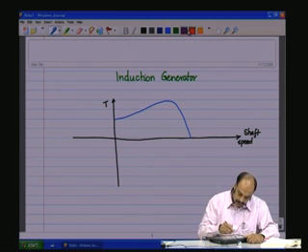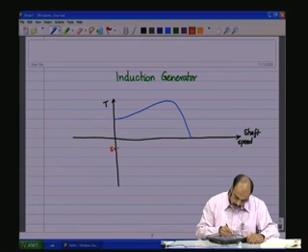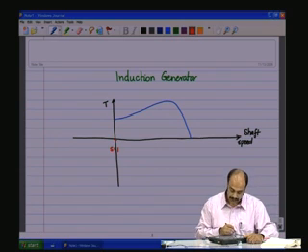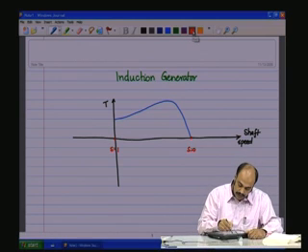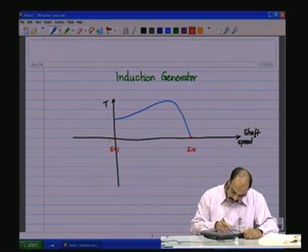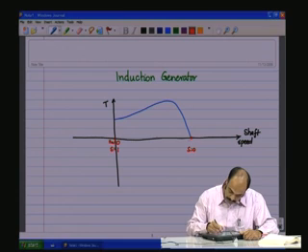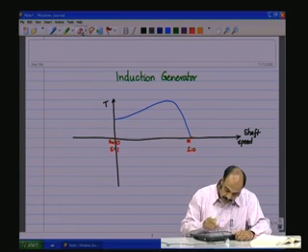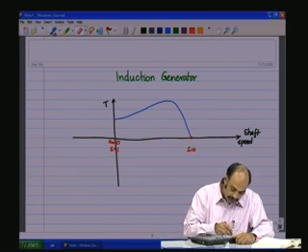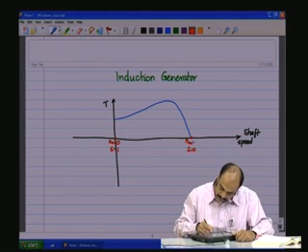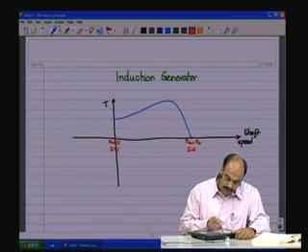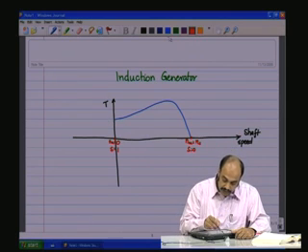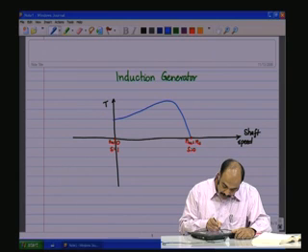is the torque that we see from S equals 1, this is stationary, standstill, to this point S equals 0, where speed-wise Nm is equal to Ns, the synchronous speed. Beyond that is the super synchronous speed, and below this one is the negative speed. In the negative speed we also saw in one of the examples that there is braking.